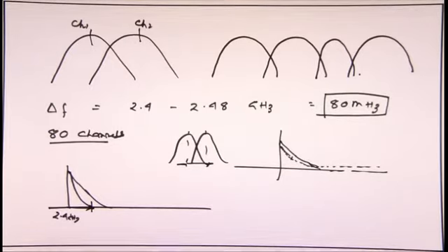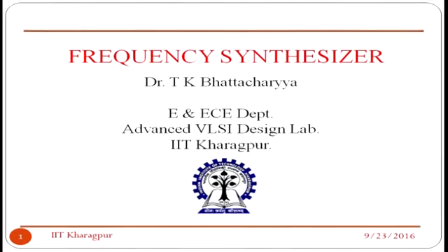Yes or no? Clear? So you understand the challenge of frequency synthesizer design: I have to accommodate a large number of channels with a stringent frequency resolution or frequency separation technique, which is always challenged by what? Phase noise. Phase noise is added with your signal, and that will give some blurring of the channels, so separation becomes a problem. So you understand this, right? So let me go with this keyword to design a frequency synthesizer.